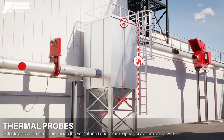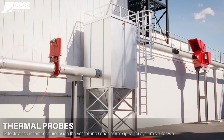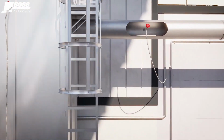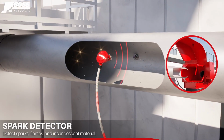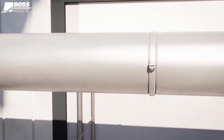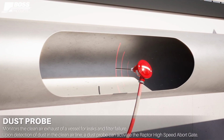Thermal probes are another additional layer of protection, where basically they can either detect at a certain set point temperature or a rise in temperature that can also activate certain equipment. And broken bag detectors or dust probes on the clean air side, if you have maybe a bag that's broken or a leak in your filter.